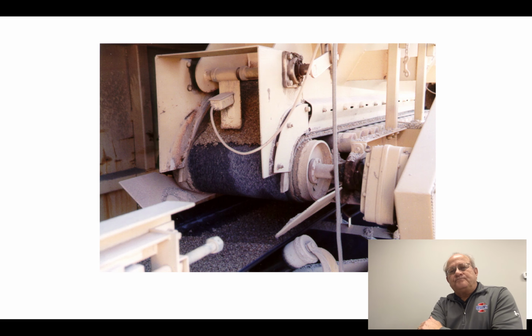All right, this is an aggregate feeder, a belt feeder. You have different size gate openings if you want. The motors on these are controlled variable speed through the plant computer system. There's a little paddle hanging down there that has a mercury switch in it, which is a no-flow switch, which will notify the plant operator that there's no material coming out if that bin would happen to go empty. So it's just an indication to shut down and wait for the loader man to get caught up.